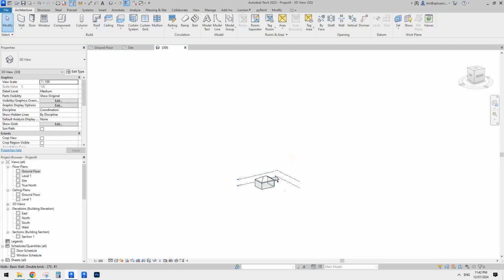But if it's still early stage, I will always move the project to match the topography. So usually what I do is I try to find exactly what the height difference is, because you don't want to move up and then move again.